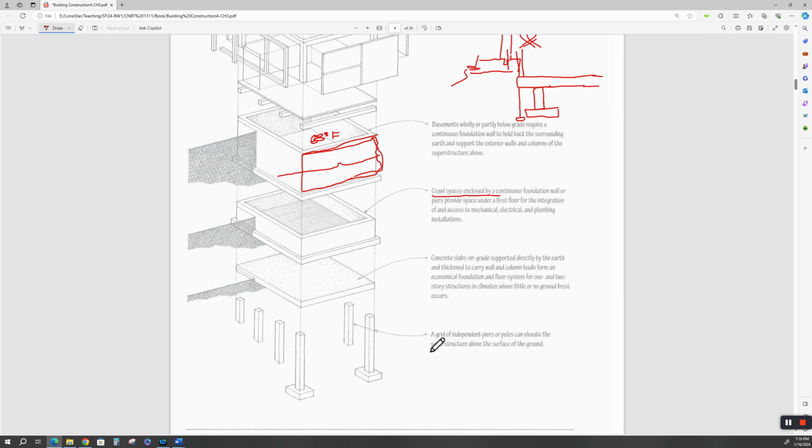So everything, the roof, the floors, the walls, the windows, the people, the loading, everything goes down to the foundation. Now, sometimes, and I know some people who have built houses down here in this crummy soil that we have, they have actually spent a lot of money having piers put down. They get a soils analysis, an actual real soils analysis, and they go down about 12 feet to the clay level, which is not affected by our drought, and they put drilled piers in. They don't put spread footings like this. They'll drill down.